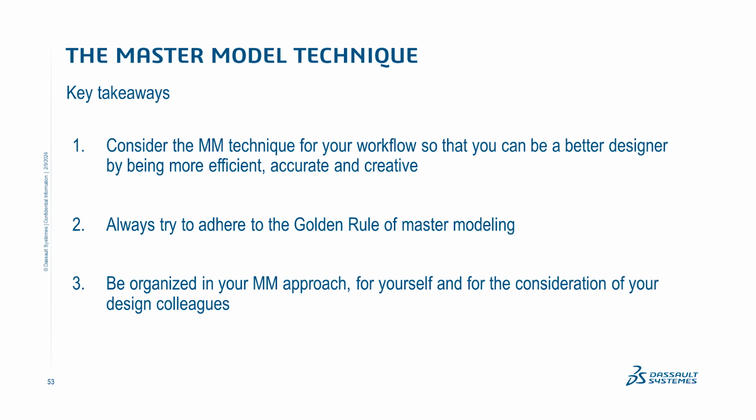And two, very important, always remember the golden rule of master model: only features that are used in two or more components are in a master model. Those features that are only used in a single part or component don't belong in the master model.